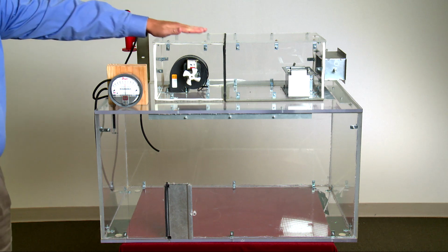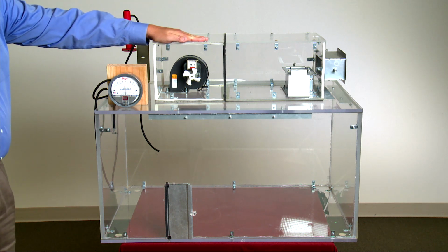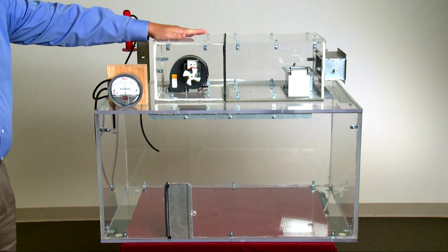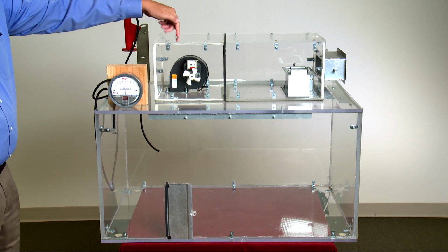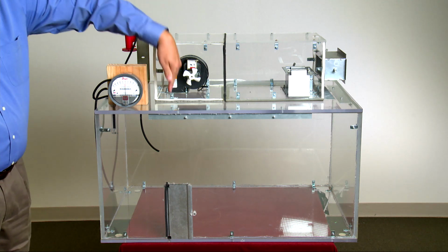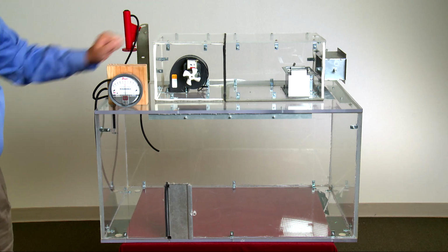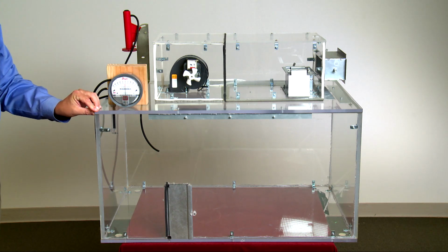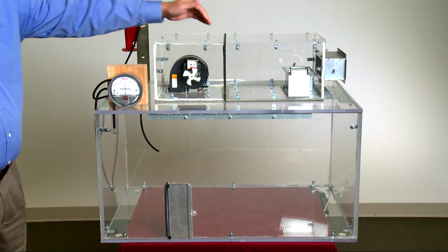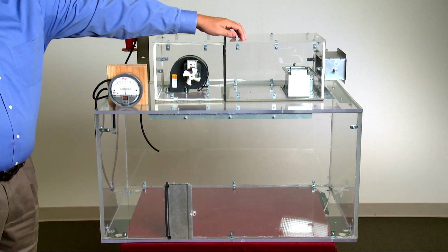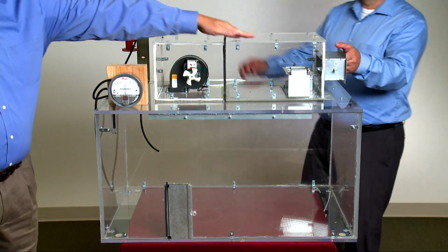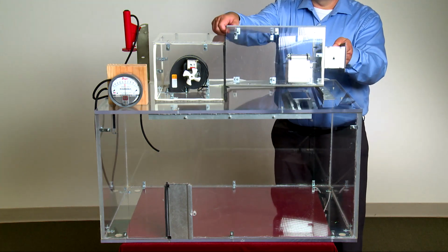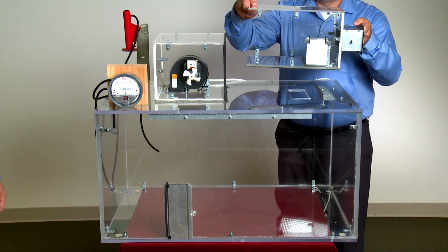Then we have our air handler mounted on the roof, which is in 2 parts. This fixed module on the left includes a supply fan that blows directly into the building. No budget for ductwork on this project, so it's direct discharge. In a real air handler, of course, you'd have coils and filters right here. This other module on the right is replaceable, so we can switch it out to demonstrate other system configurations.